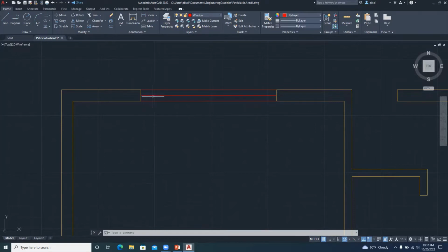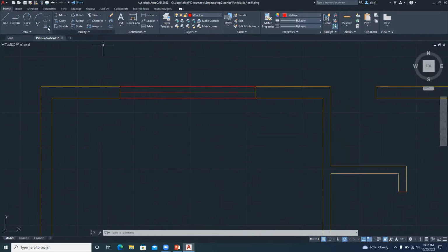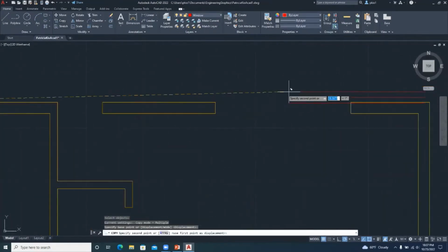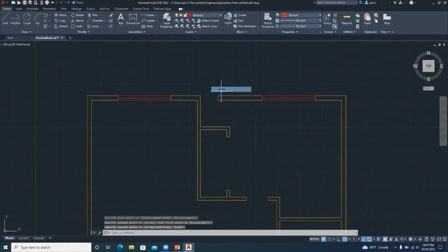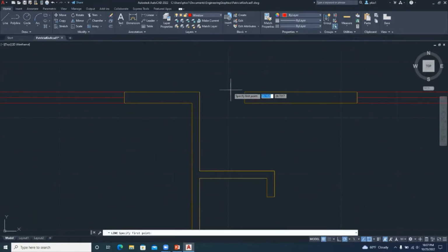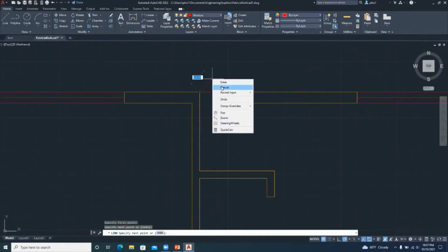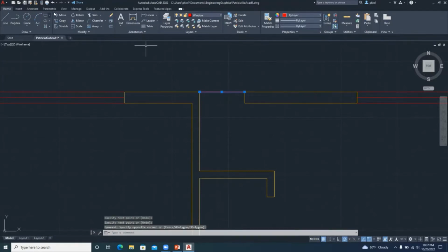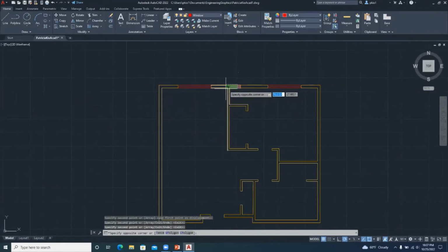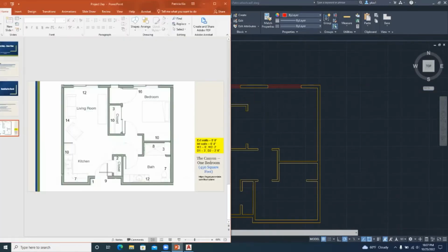So for more detail, we can offset it before. Let's keep it simple and keep 3 lines. So we'll copy this window, select it, copy, and paste here, and then we draw in this one. Enter, and select it, copy. So we have the 3 windows in the drawing. 1, 2, 3. There are no other windows here. So let's put the doors. We have 1, 2, 3, 4, 5 doors.